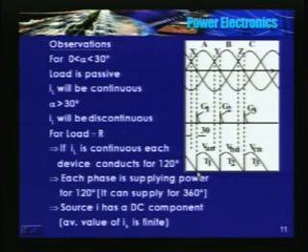So if I had a load which is purely resistive, current cannot flow beyond this point. So the thyristor turns off of its own, because current has become 0. Till you trigger the next thyristor, load voltage is 0, because none of the thyristors are conducting.